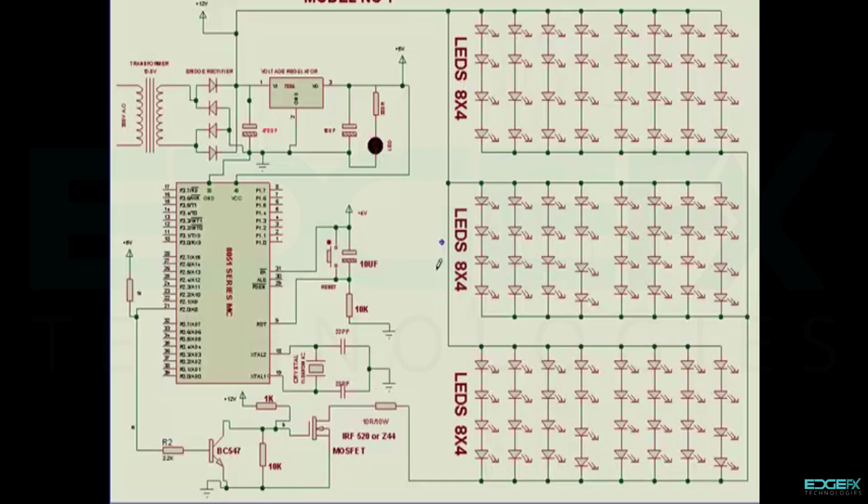Depending on the requirement, the duty cycle is given here for changing the intensity of the lamp, the LEDs. The other advantage is that the program is made so that in a given time interval, this light will slowly go to lesser and lesser intensity starting from full intensity. For example, if the duty is 10% here, then the LED glows to the extent of 90% when the duty cycle is 90%. Here the LED glows with the 10% duty cycle.